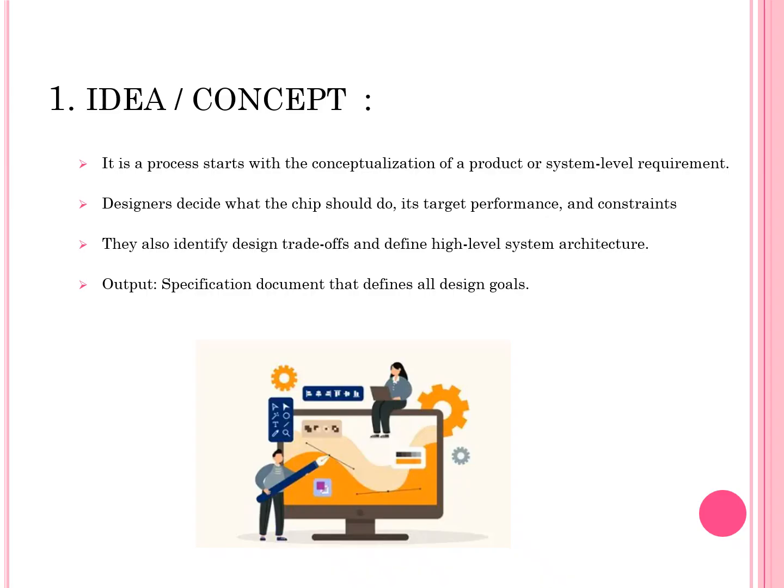They conduct a feasibility study to evaluate whether the desired functionality and specifications can realistically be achieved within the available technology and process nodes. This stage also involves identifying design trade-offs. For example, balancing speed versus power consumption or area versus performance to ensure optimal design decisions early on.